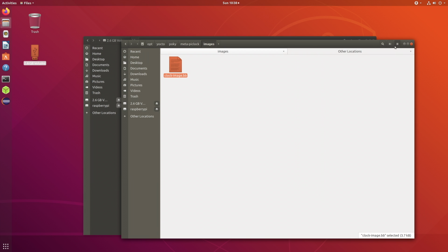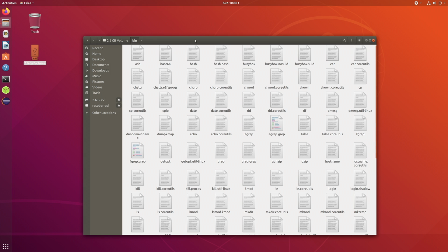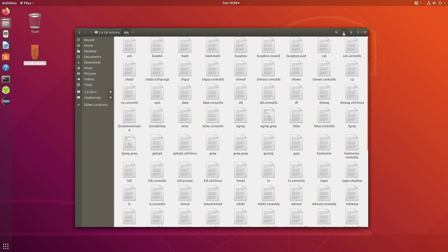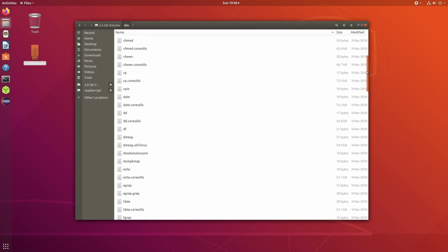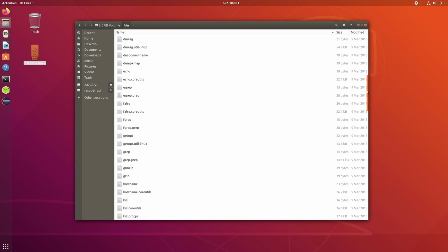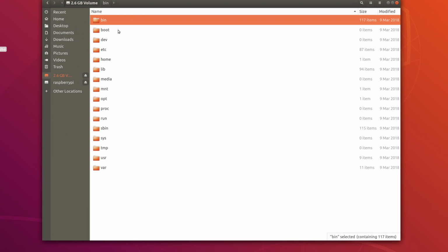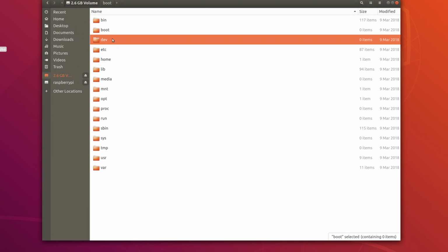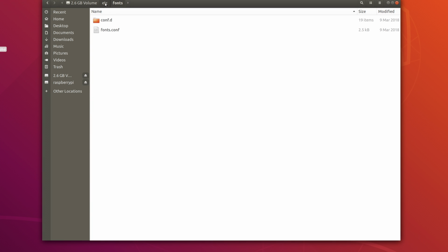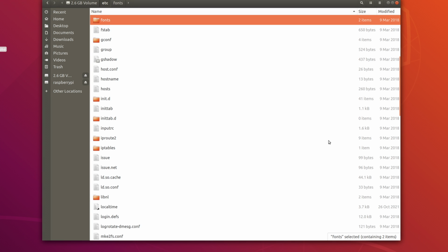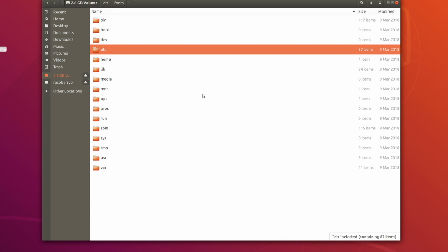And when you go onto your, let's go to the file system. So here we are in our file system now. This is the bin folder. Here you can see it has all the binaries which we asked Yocto for. So Yocto has made sure that we get all these binaries here. And is there anything in this folder? No. What about the dev folder? Nothing here. In etc we have some fonts, everything which was required, which we asked Yocto for.